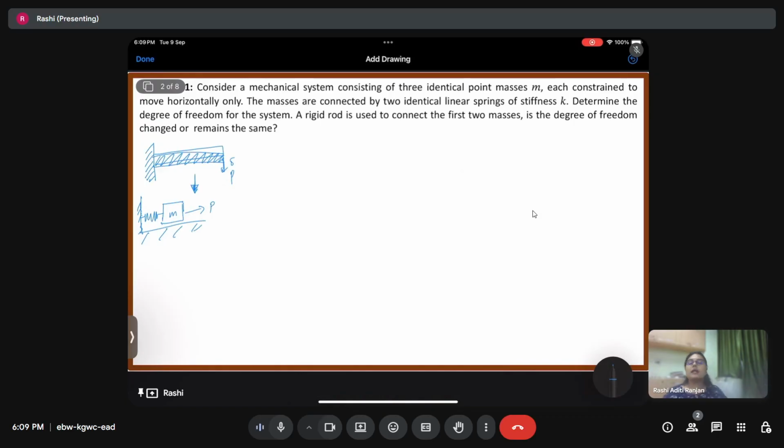Introducing a multi-degree of freedom system to model a particular continuous system gives us better accuracy. For example, for the cantilever beam, instead of modeling it as 1 degree of freedom with one mass point, we can divide it into 4 mass points connected by springs. So it becomes a 4 degree of freedom system, and the final displacement of the last mass can be considered as the deflection of the beam at the point where the load P is applied.